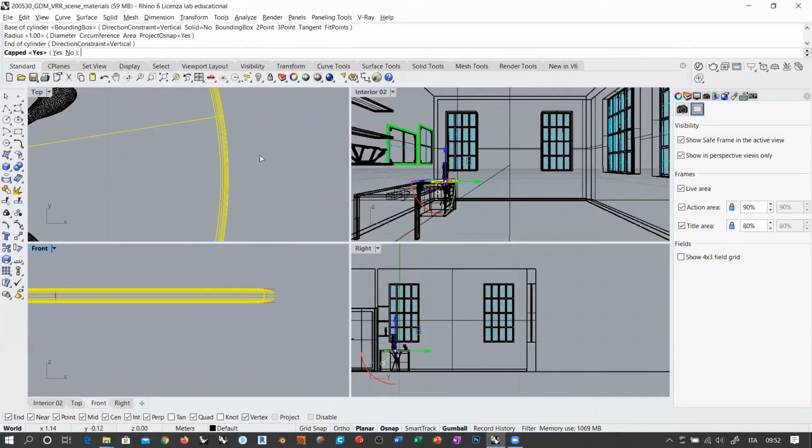And as per the height, I will take this one. And Rhino asks, because texture mapping is something that belongs to Rhino, not to V-Ray. V-Ray will use this texture mapping, but it's not part of the V-Ray workflow, okay? It works also with Cycles. That's what I mean. If you want this mapping to be capped, then you just confirm that you want it to be capped, like here, okay?